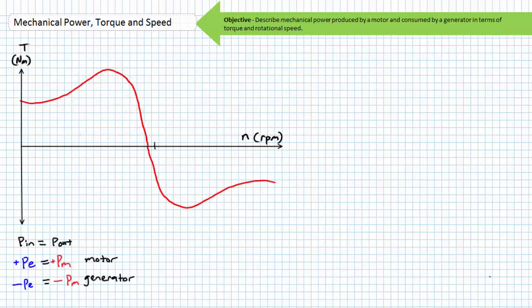Returning to an expanded speed-torque curve from our earlier motor examples, you'll realize I previously only gave you a small portion of the curve, that where torque was considered to be positive. If we consider only a case where things are rotating in the clockwise direction, what would happen if an outside force, let's say falling water, moving wind, or expanding steam, was to grab the rotor of a three-phase squirrel cage induction machine and spin it faster than synchronous speed? You would find this extended speed torque curve that looked like this.